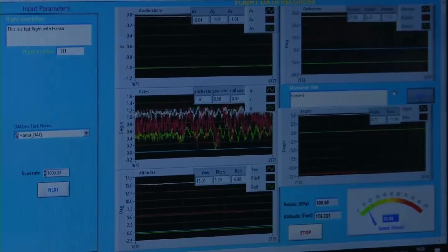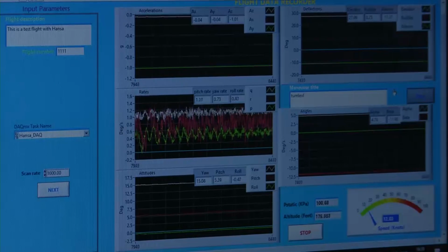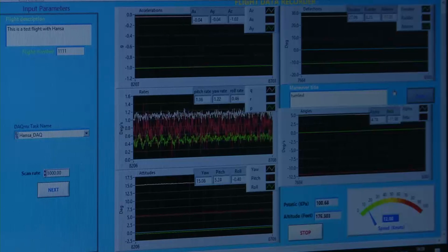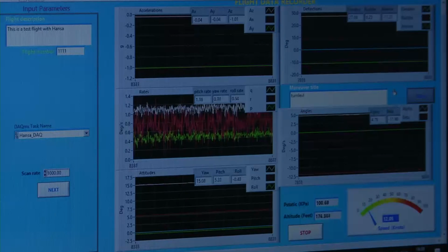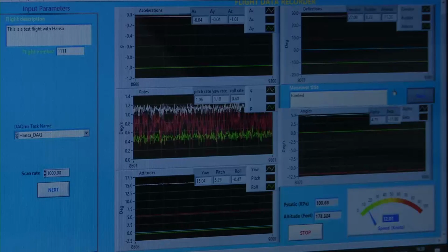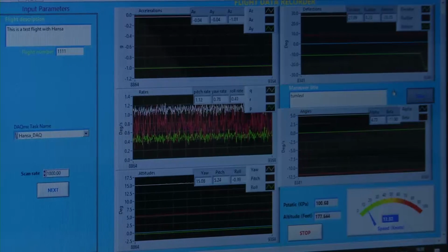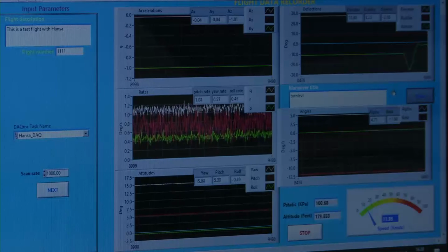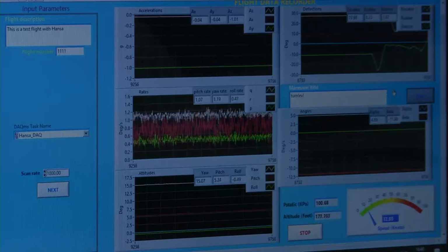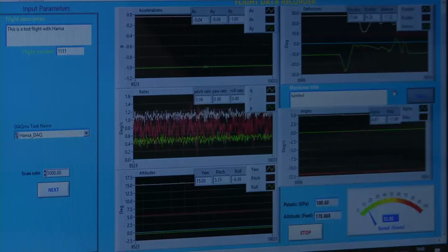Because suppose while you are trying to build an autopilot and you want to have a particular restriction on turn rate, climb rate, and you have limitations such as your servo cannot go beyond a certain limit or certain degrees, you want to design such that the sizing should be enough so that your restrictions can be met. So that's why while performing in manual mode, you have to collect these data, and based on these data you can direct your autopilot to give this much percentage of gain when performing those maneuvers.